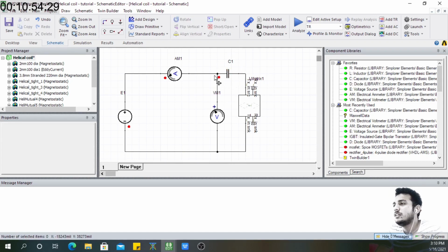Make sure that the polarity is on the right side. So I guess this red dot means negative polarity, and though it doesn't matter that much, you can always swap the direction if something happens. If you get a drastic phase difference, like a phase difference of 180 degrees, then you might have problems with the measurements, right? So in that case, just make sure that the polarity is in the right place.